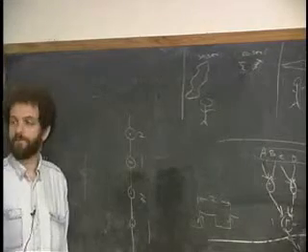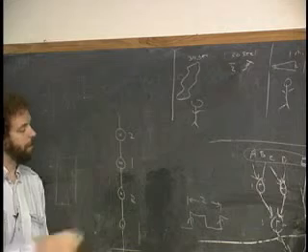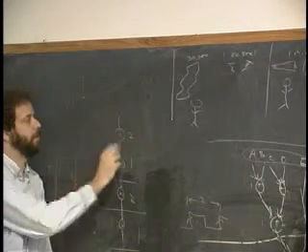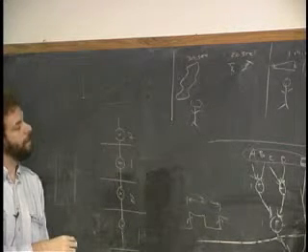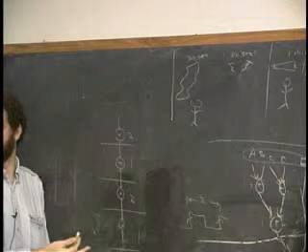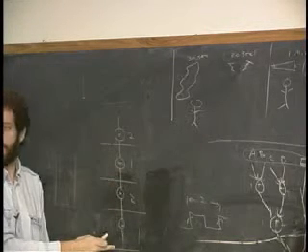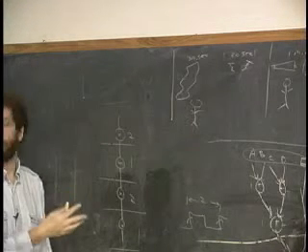That's really rough, okay? Because first of all, we need a register on the output. Then we surround the ones that have the longest time with registers. And we're going to assume there's one up here, okay? Well, there's nothing left to do. We have 8 here. We have 1, 2, 3, 4 time units, a total latency of 8. And this is sort of a worst case, okay?